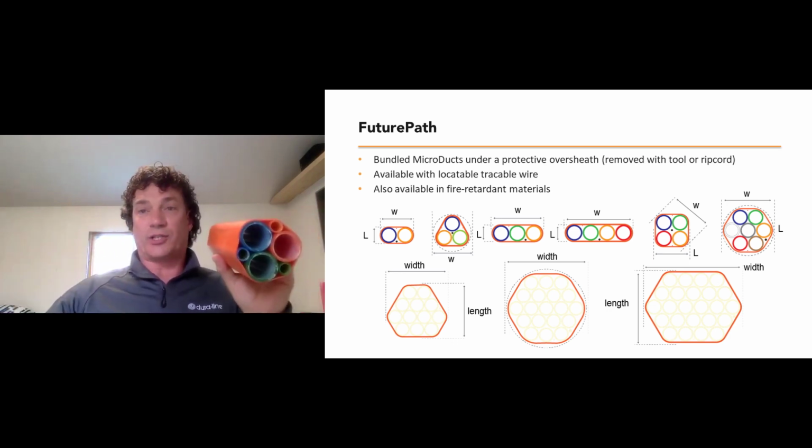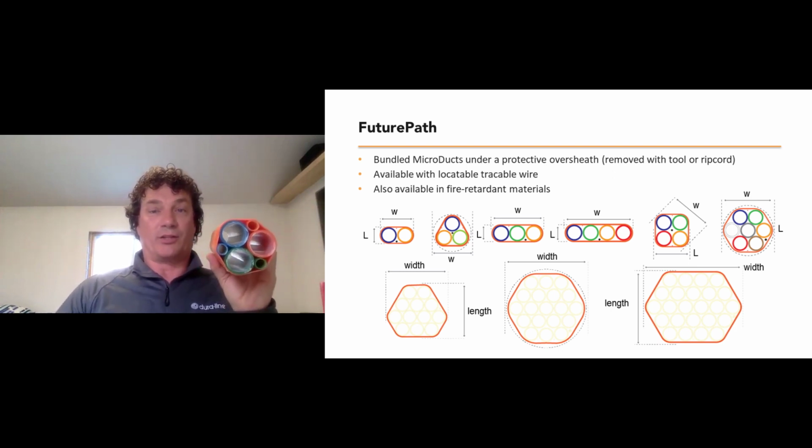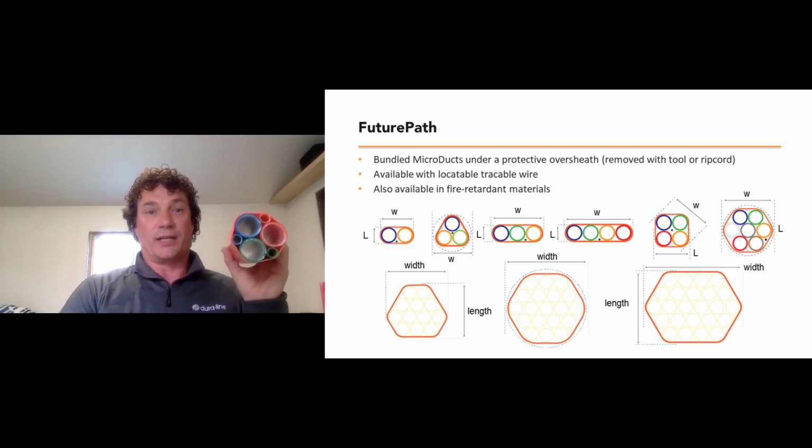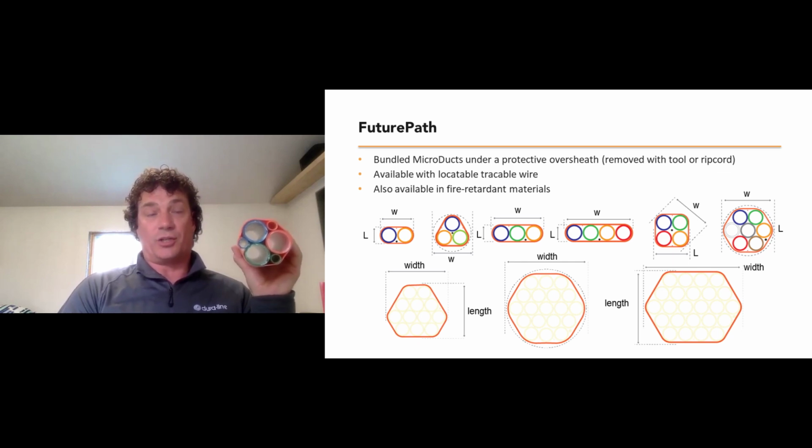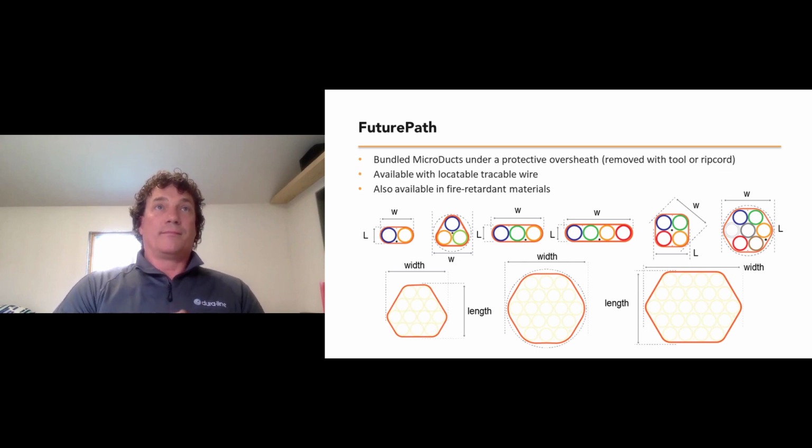Or we can take a look at traditional sizes in a mix of Microtechnology and traditional sizes. So if your company is looking at changing your fiber plant, but you have a lot of existing fiber that is traditional, there's an offering that you can mix the two of them together. So the MicroDucts will provide additional space for future fiber and future additions and give you the ability to branch out along the path. Taking a look at capacity in a traditional method versus a Microtechnology method.